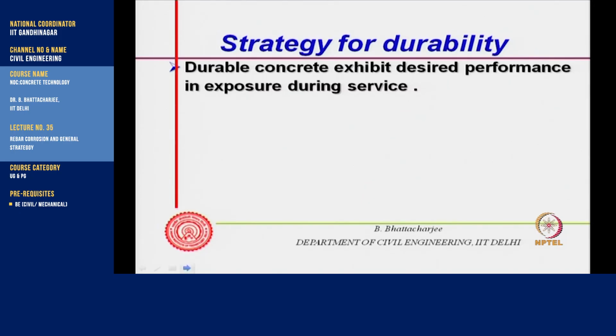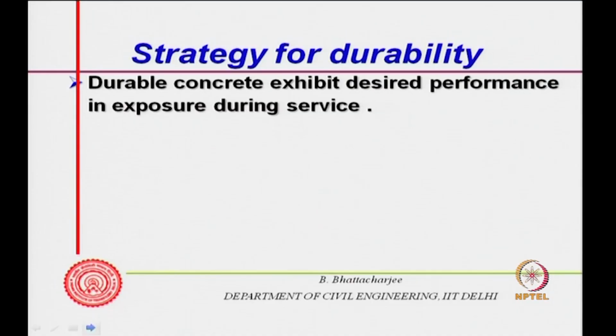Possibly carbonation is a function of the square root of time, which is experimentally validated. Many things couldn't be experimentally validated because of the long term required. Accelerated tests quite often may not represent the real situations.